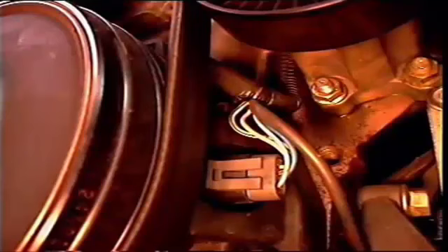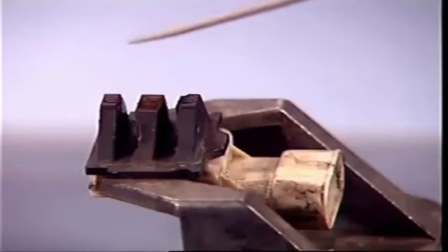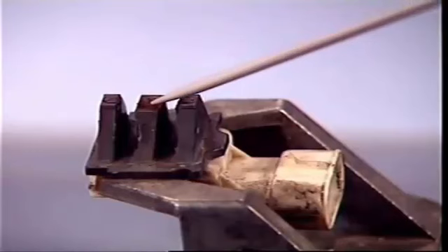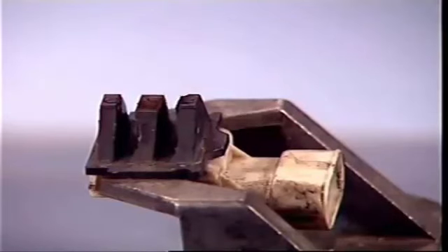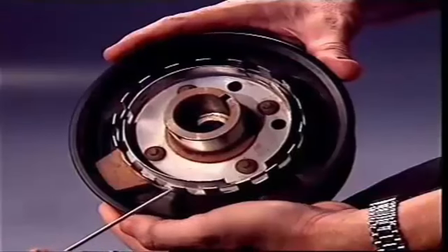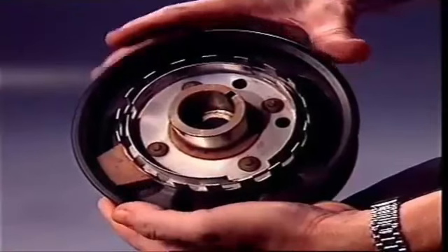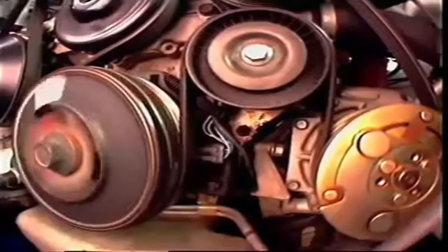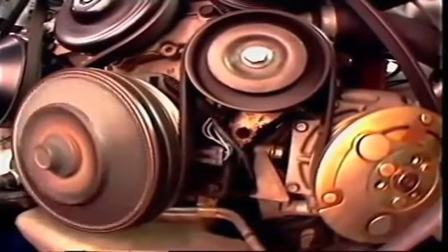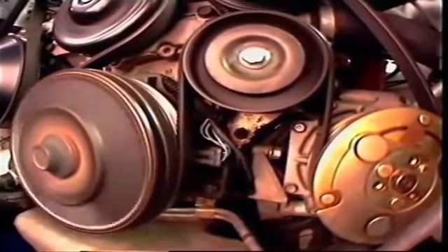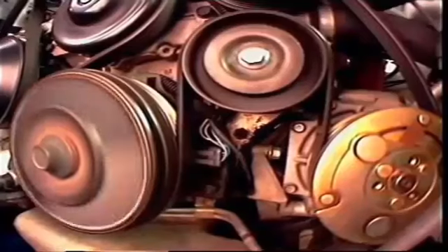Identification of each pair of cylinders and a signal for their triggering is provided by a dual crank sensor fixed to the engine timing cover. This contains two Hall effect switches sharing a central magnet which forms two air gaps between them. Two concentric interrupter rings with a number of blades and windows and mounted on the rear of the crankshaft balancer rotate through the gaps. The voltage signals provided allow the ignition module to identify which pair of companion cylinders must be provided with ignition.